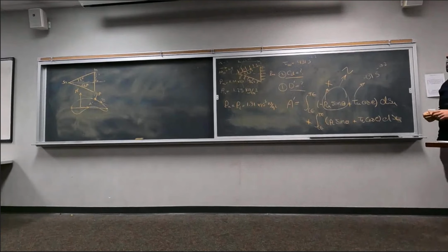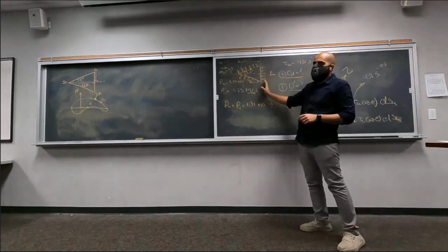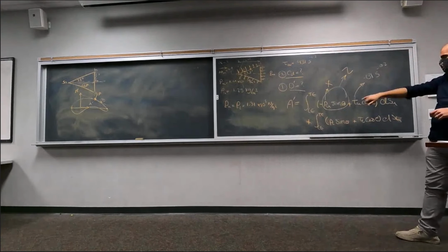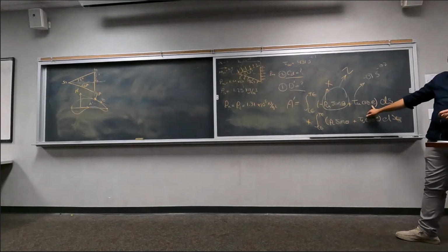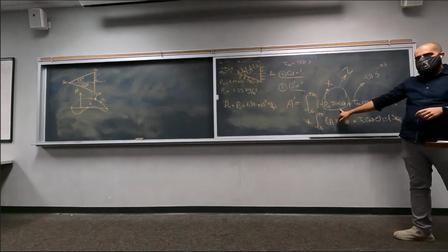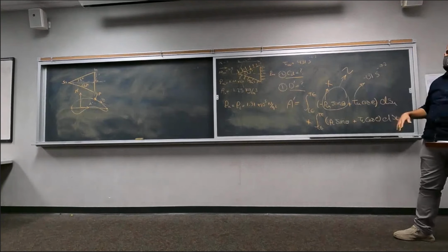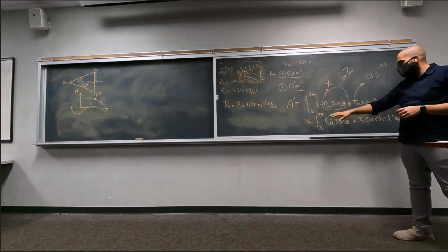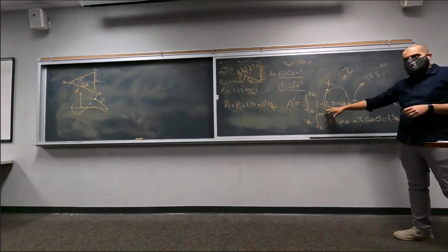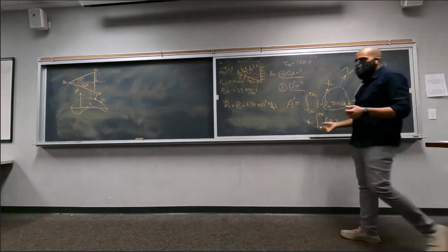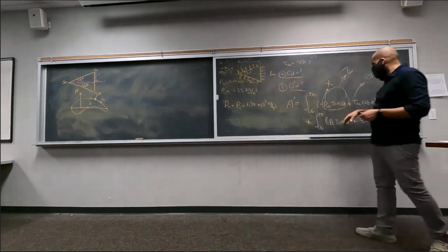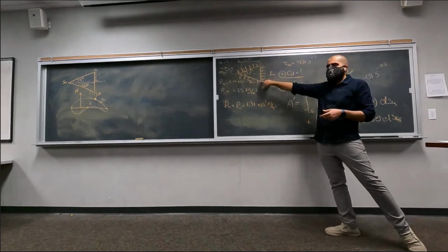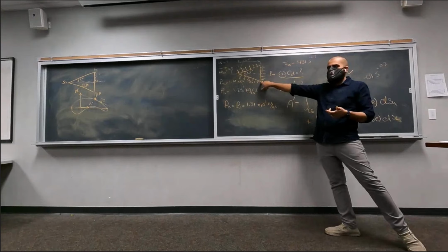So let me ask you this: what is going to happen to this integral on this surface? What is theta on that surface again? 90 degrees. So what is cosine of 90? 0. What is sine of 90? 1. Okay, so the shear stress is not going to contribute to drag on that surface. So you're going to get the integral of PU ds, integral of PL ds. So essentially you're going to get PL multiplied by this length, negative sign, plus PL on the lower surface, multiplied by this sign. Does it make sense?